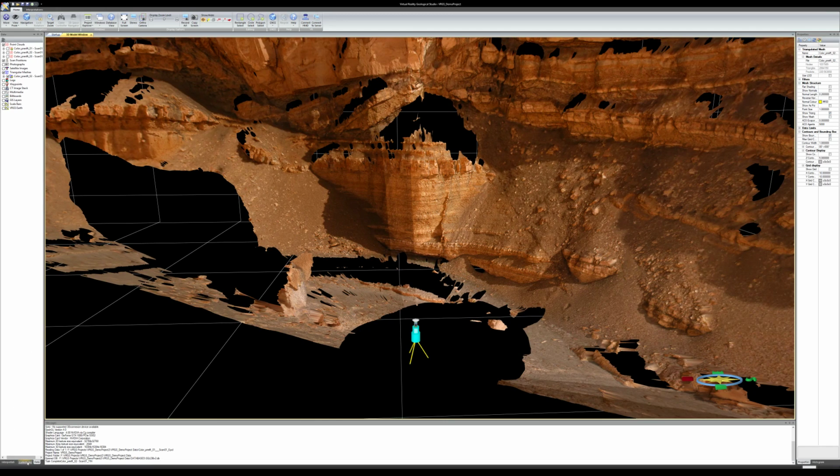A little bit on the layout of the screen. We have on the left hand side our data tab, which is where our data is stored. So there's things like our point clouds, our meshes, satellite imagery, things like scale bars could also be in there. We have our interpretations tab, so these are the things that we've created in the model, so they can be polylines, structural measurements, and a whole variety of different things. Collections are descriptions, so there might be things like facies descriptions or grain sizes or lithologies or horizon names. They're things that you use as descriptions, but you can't visualize them directly as an object in the 3D view. So they don't have any checkboxes to switch them on and off with.